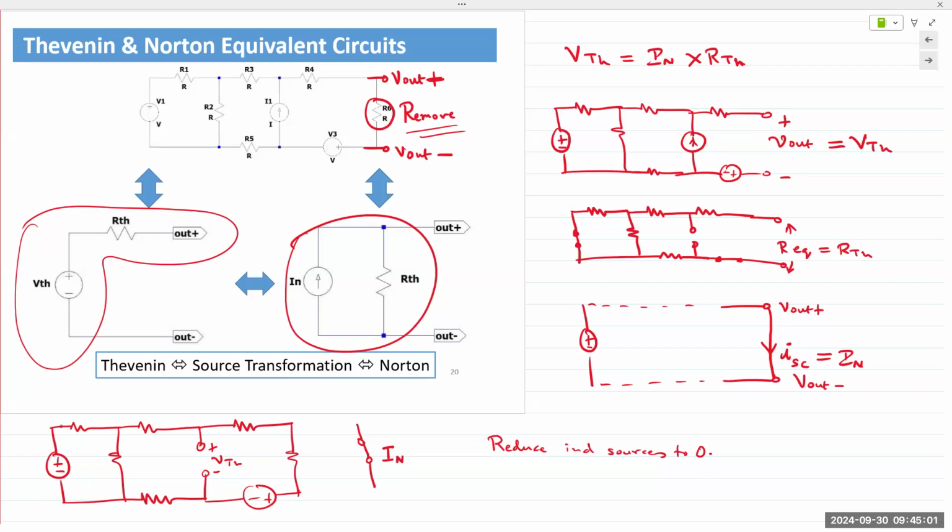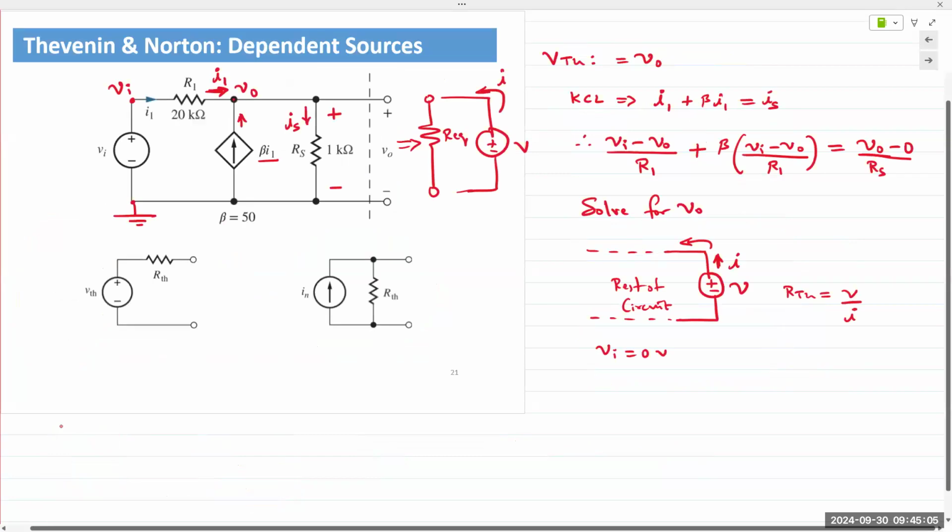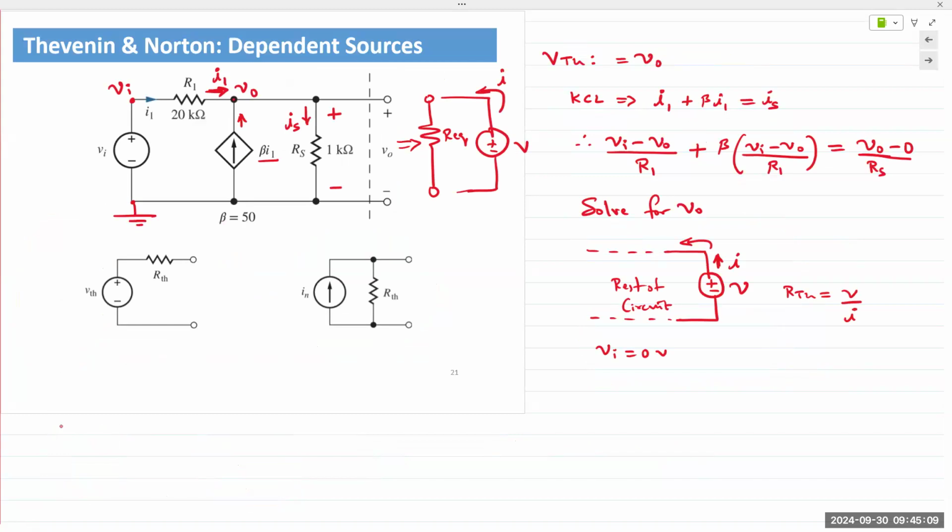And then of course, the reason why we need to be able to find all 3 quantities is because if you have dependent sources, well, the first reason is, of course, if you have 3 quantities related by Ohm's law, you only need 2 to find the third, right? But if any one of those 2 quantities is incorrect, then your third answer will also be incorrect. So you'd end up with 2 wrong answers out of 3. So you always want to find all 3 of them to verify your answers.